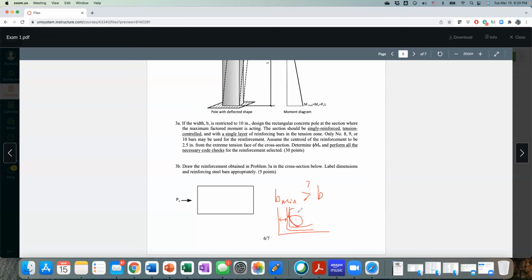So that dash line is invisible, but that's how we bend the stirrups, right? Remember? And from the center of the bending radius, which is actually lined up with the corner bar here, you have a 2ds. From the notes, ds is the diameter of the stirrups. Now after that, you have this half of the bar size, and then you have a minimum spacing between this bar and whatever bar you have in the middle or on the side, like CS.